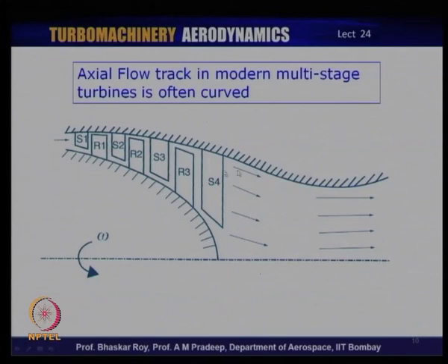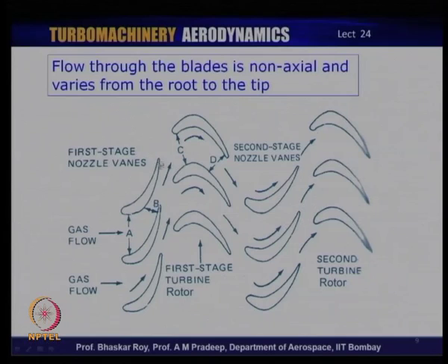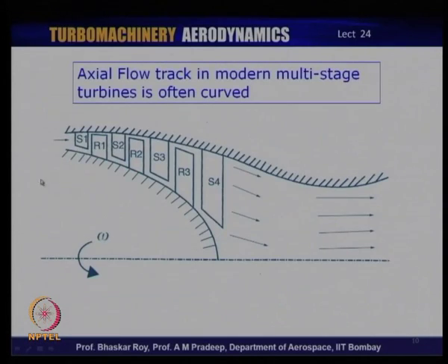So, this curvilinear passage of flow first goes through the blades like this, it comes in, goes like this and then goes like this. It executes a lot of curvature at a particular radial station if you take a cut, and then if you look at it sideways, it goes through a passage like this. Okay.